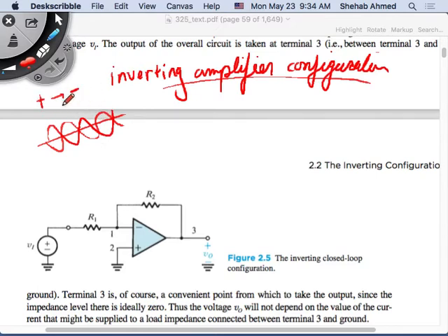That's what this will do. But it will also change its magnitude. So it's 180 degrees out of phase, and it can change the magnitude of the output as well, right? Can make it larger, can make it smaller, depending on how we design this. What is the voltage gain of this circuit that we're going to add around this op-amp to make a new closed loop gain, right?